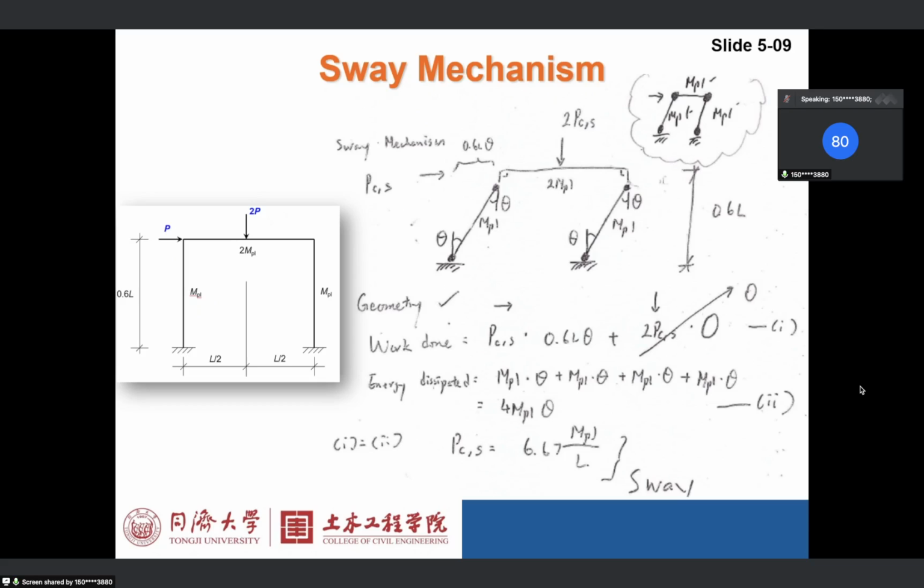It appears like that. Again, somebody says this is strange, why does it happen here? Again, this is because of the weaker column. If the column has the same cross-section as the beam, it will look like this. But the column is weaker, so it will look like this.